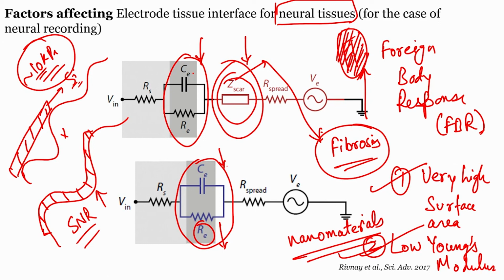signal. Now this brings us to the end of this session. What are the takeaways? Takeaways are as follows. 1. In order to model any kind of tissue electrode interface, you need to know what kind of resistors and capacitors are there. We took a case example of breast tissue, wherein there were two double layers, which are capacitors on either side offered by the tissue electrode interface, and the tissue impedance itself and the medium.